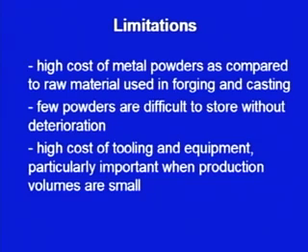Moreover, high cost of tooling and equipment is particularly important when production volumes are small. We have quoted a figure also, and depending upon that figure we can say the break even can come earlier or it can come later. So, high cost of tooling and equipment has to be justified by the production volume. If the production volume is relatively small, then we have to justify the higher initial cost of the dies as well as of the equipment.